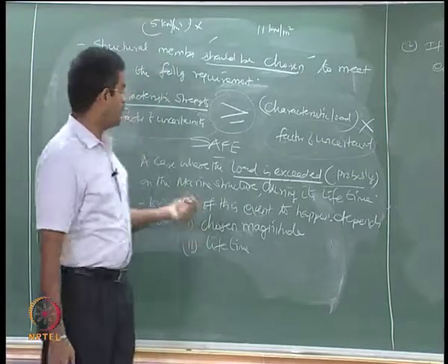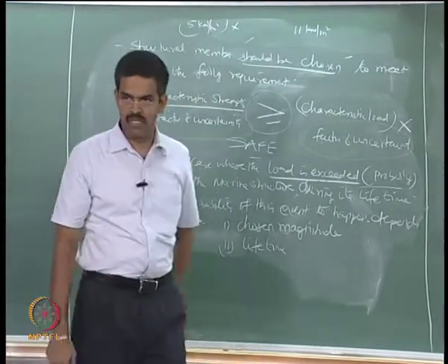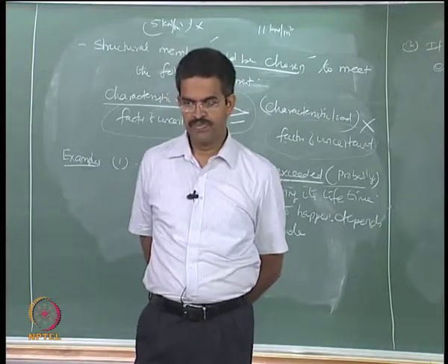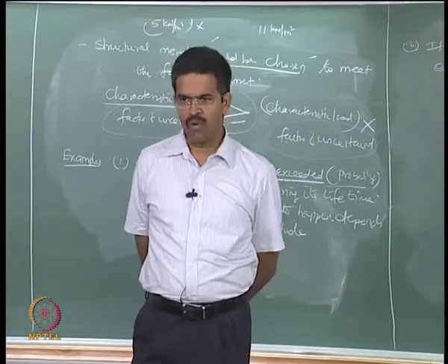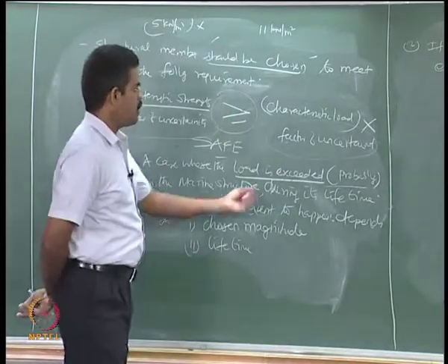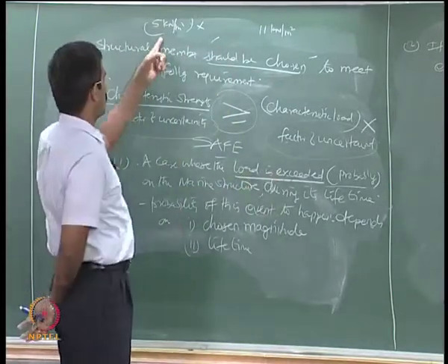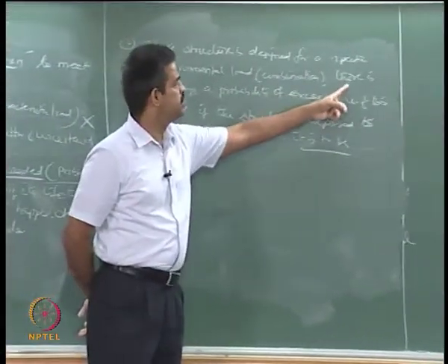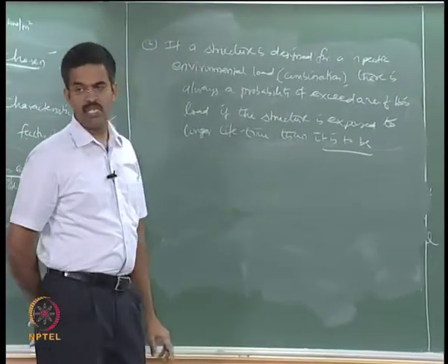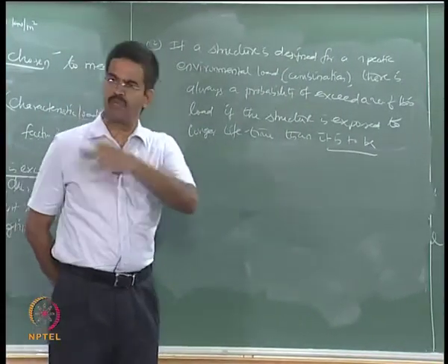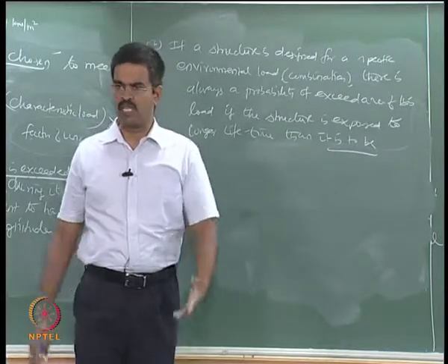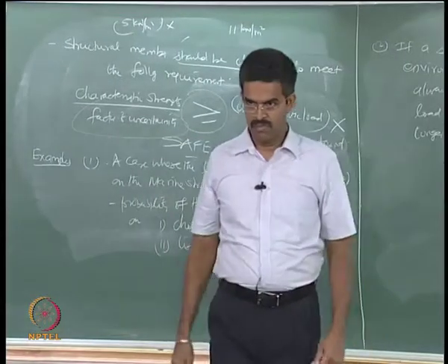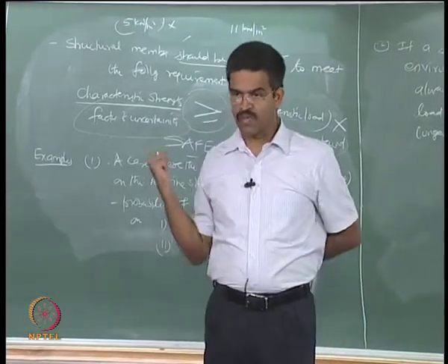So, the ultimate load design mechanism as such may look like a wrong process. The process as such is not wrong, it is that the value you are saying is exceeded is wrong. You have chosen a wrong number, you have chosen a wrong lifetime. You said it is 10 years, but you are allowing the structure to remain for 50 years. So, you are saying it is exceeding, therefore, the factor of uncertainty should be revised because it is not giving safe results. Is that clear?